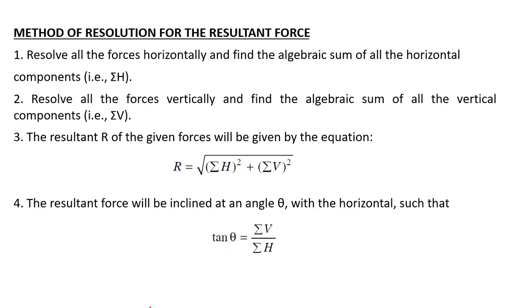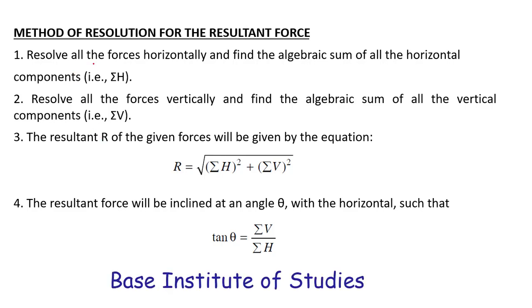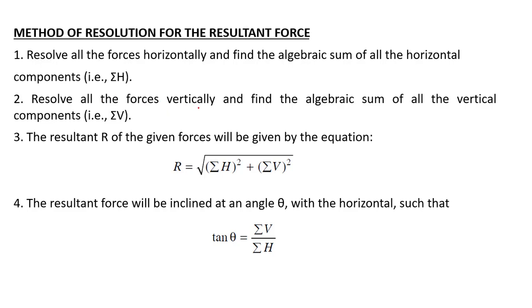Now, method of resolution for the resultant force. If there are a number of forces and we have to calculate the resultant of those forces, then we need to resolve all the forces given in the force system, and then calculate the resultant. So what's the process? First of all, resolve all the forces horizontally and find the algebraic sum of all the horizontal components, that is sigma H. Second step is to resolve all the forces vertically and find the algebraic sum of all the vertical components, that is sigma V.